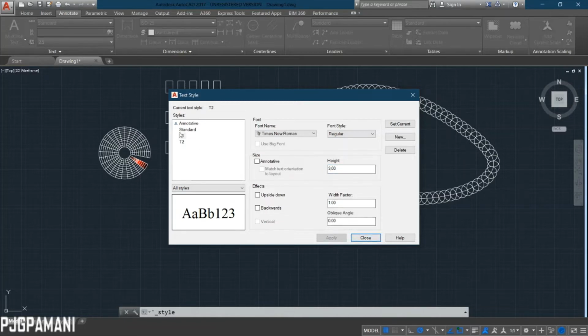Then, okay. As much as possible, I do not recommend that you use annotative scaling. With annotative scaling, you can draw anything starting from 1:1 or any object with any type of scale, but you need to set it later on when you transfer it to layout. So as much as possible, let's stick with regular scaling, because annotative is confusing. I don't really use annotative. But I'll teach you later on a shortcut when it comes to scaling floor plans or specified scaled objects.